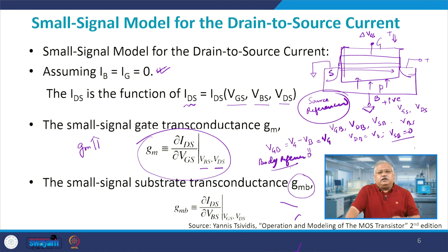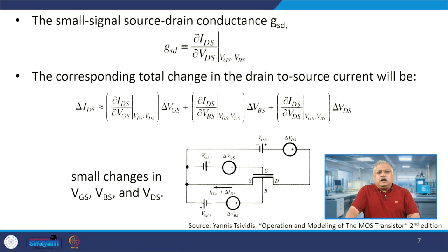And if there is some leakage happening in the substrate, if there is some problem with the substrate, if it affects my overall drain current, I will be in a big problem, and that is the reason I want it to be as low as possible. Let us come to the third one, which is known as GSD or GDS, as we refer to it, and that is drain current with respect to a change in the drain to source voltage.